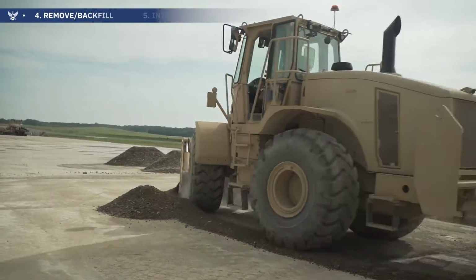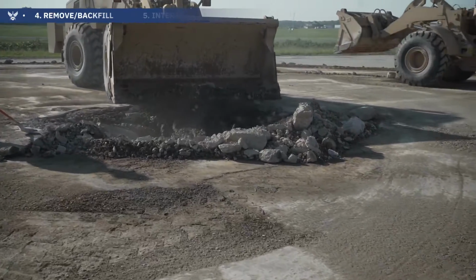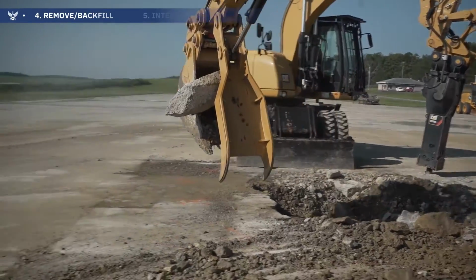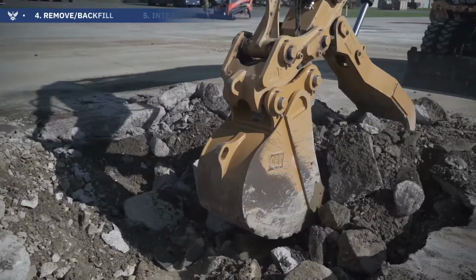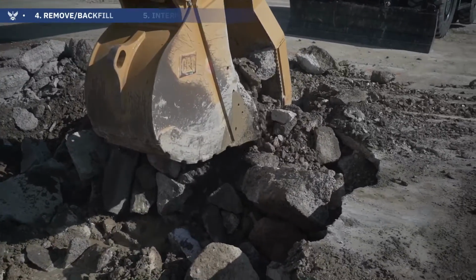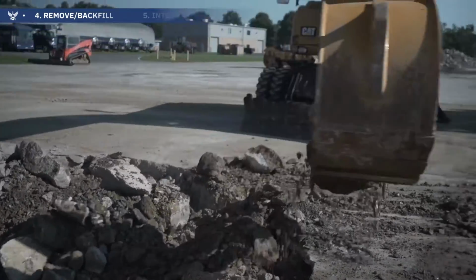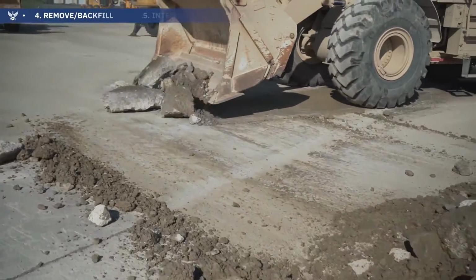Choke ballast over debris crater repair method. Using the excavator, break and remove pavement in the crater bottom that exceeds 3 feet in diameter. Using the excavator bucket or moil point, begin breaking and removing upheaved pavement to marked upheaval limits.